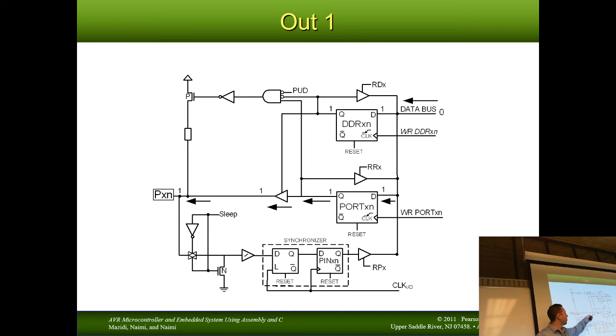Interestingly, note that because we're driving this, we could actually read in from the pin register and see what the output is. It's something we could do. So let's say that just for fun, someone decided to be bad and hook this directly to ground. They physically tied this pin to ground. What happens when you try to drive 5 volts to ground with just a wire?